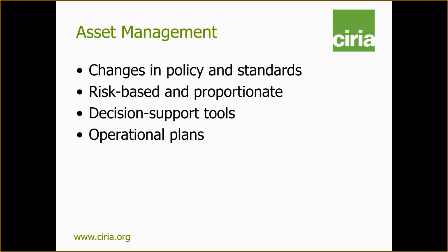The manual reflects changes in asset management policy and standards, and it draws on lessons from past flooding. So it has been updated to reflect ISO 55000, the new international standard on asset management, as well as best practice in highway asset management and network rail policy on asset management. The asset management processes and systems should question whether an asset is still needed, and asset management should be risk-based and proportionate. So, for example, the level of detail in hydraulic assessment should be based on the risks, the land use, and the sensitivity to flooding.